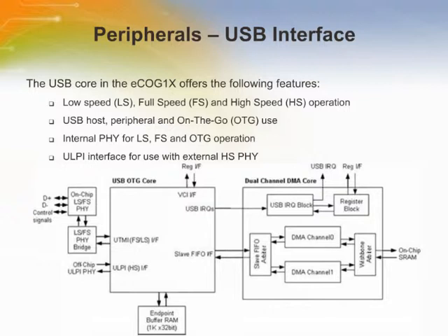The USB core requires 4 kilobytes of working memory used for the endpoint data buffers. This is taken from the top of the internal memory and cannot be accessed directly by the processor. Reading and writing to this memory is always done through the USB core FIFO registers or with the DMA peripheral and the slave FIFO.